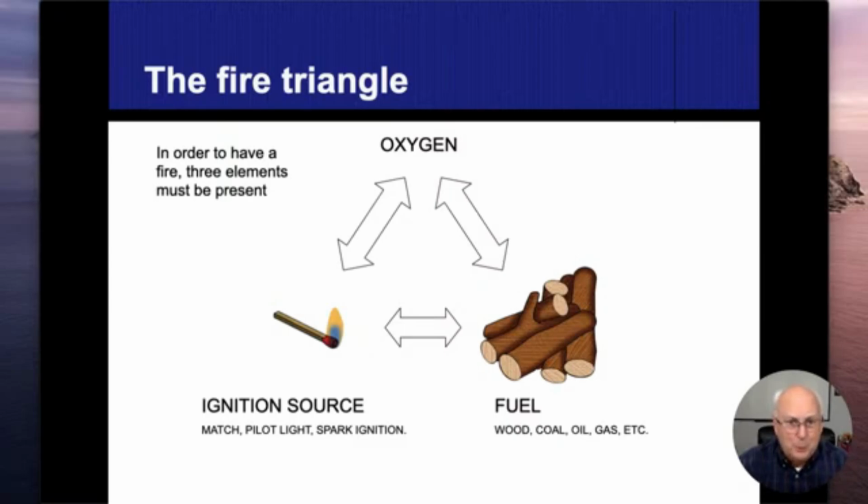We do put carbon monoxide alarms inside of our residential buildings. And I think that's important enough to say that in the state of Illinois here, we do have a carbon monoxide law. So we should be having a carbon monoxide alarm within 15 feet of every bedroom.